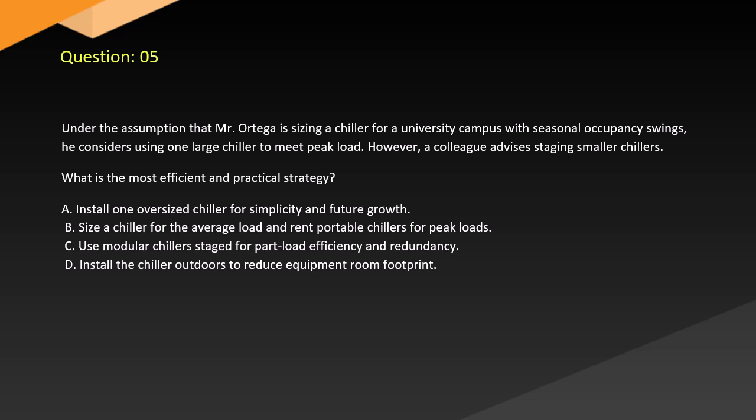A. Install one oversized chiller for simplicity and future growth. B. Size a chiller for the average load and rent portable chillers for peak loads. C. Use modular chillers staged for part load efficiency and redundancy. D. Install the chiller outdoors to reduce equipment room footprint.